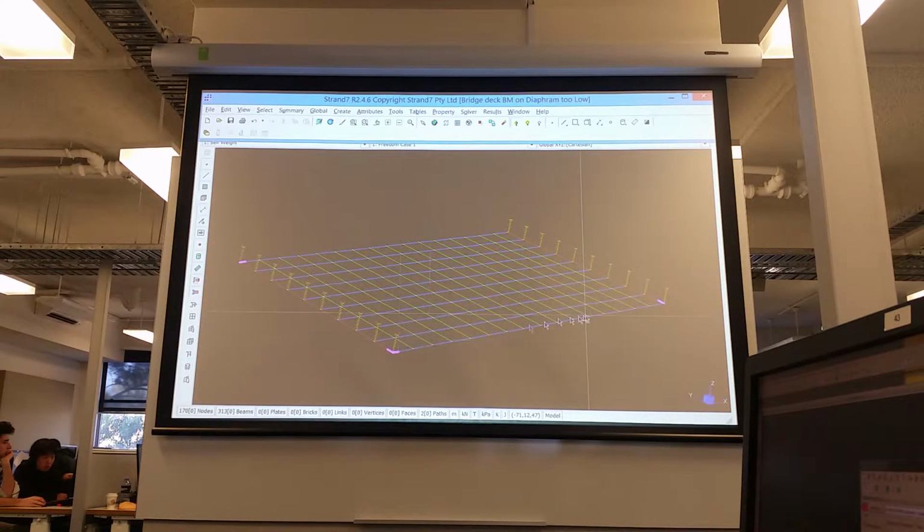It doesn't make such a huge difference for the longitudinal members because they're directly loaded. So the bending moments in the longitudinal members is really governed by the position of the load and the magnitude of the load. But for the end diaphragms, the bending in these really depends on the amount of twisting from the longitudinal beams, and the bending moment generated by the twisting depends on the stiffness. So the transverse members are more sensitive to the stiffness.